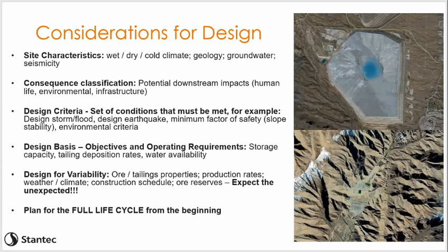Is your design resilient enough to handle things like that? Can you handle a change in production rate and an increase in construction schedule? Are you ready for severe weather and climate change? Can we handle a change in ore reserves? Say the mine company approaches you and says, we have 100 million more tons of tailings we need to store. Can this facility manage it? Or could we think about raising the facility and raising the dam? These are all things you have to keep in mind as you work through the early stages of these projects: making sure the projects are flexible enough to handle all the curveballs that are certain to come your way.